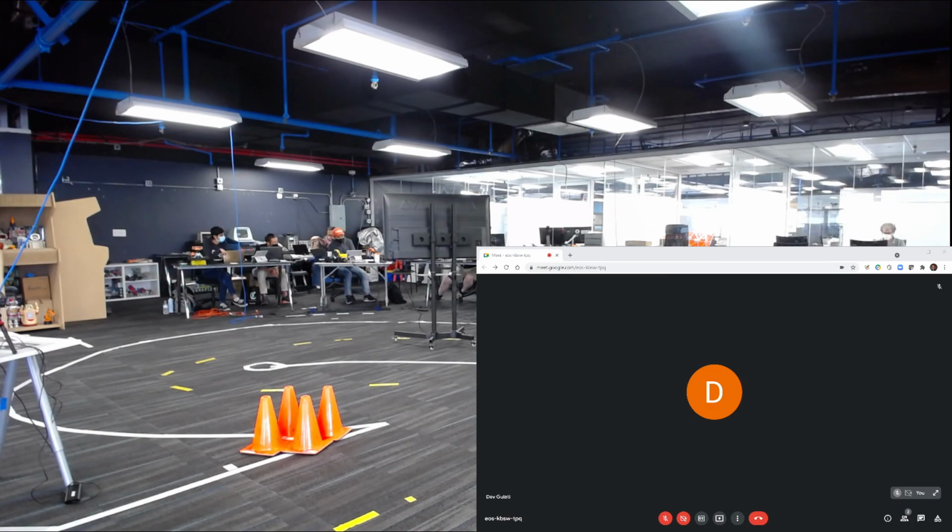Dedicated graphics cards for this simulator, right? I'm just trying to see whether I can run Autoware. I should install Autoware on my laptop, but my graphics card is dedicated. If I can run a simulator, then probably I should install Autoware. You won't be able to, and the reason is that the version of the simulator that works correctly with Autoware.auto is a slightly older version, and it's only available as a Docker container. The only way you can get access to a graphics card through a Docker container is with NVIDIA's container toolkit, so it only works with NVIDIA right now.